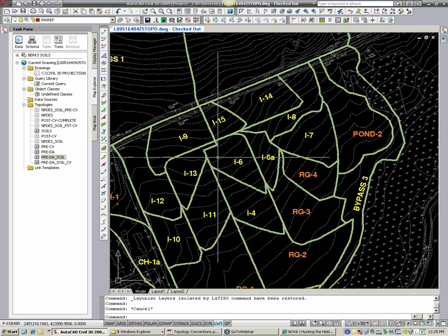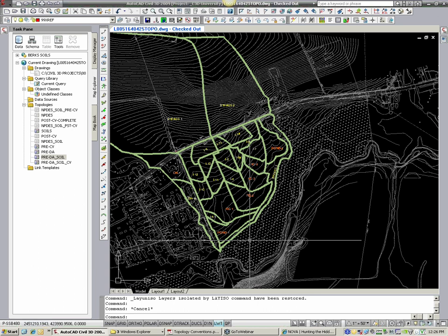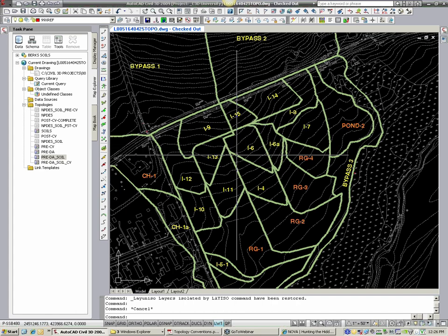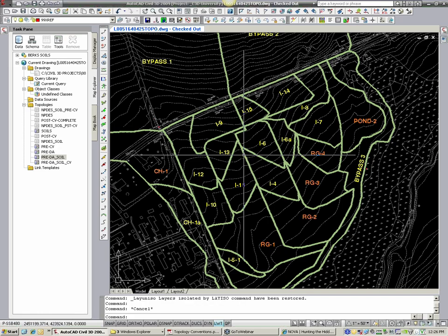And as we're doing this, keep in mind, you're doing two things at once. You're doubling up on your time, because it's not like you're doing the stormwater management and then somebody else has to do the drainage exhibits, which is a whole other 4 hours after. You're doing both at the exact same time, getting your drainage areas, getting everything ready to calc, and essentially you're just going to XREF this. So when you're placing this text, place it so it looks nice, and you can just XREF it into an exhibit, put a border on it, and bam, there's your drainage area map. 2-for-1 deal. So keep that in mind. That's all about optimization.